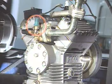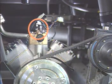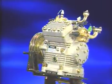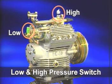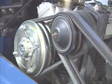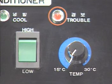A low pressure switch is installed on the compressor suction pipe, and a high pressure switch is installed on the discharge pipe. As safety devices, low and high pressure switches sense malfunctions of the air conditioning system by pressure and stop compressor operation by turning off the magnetic clutch and turning on the warning lamp.